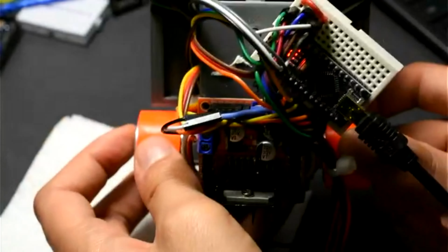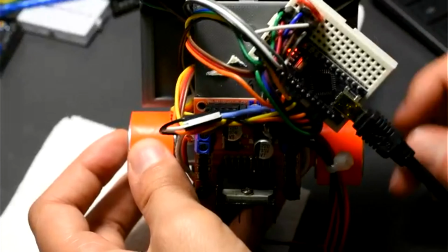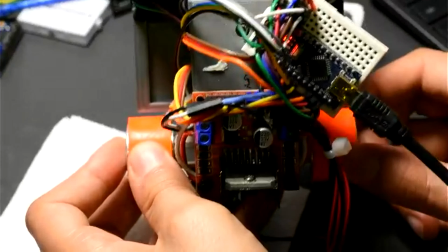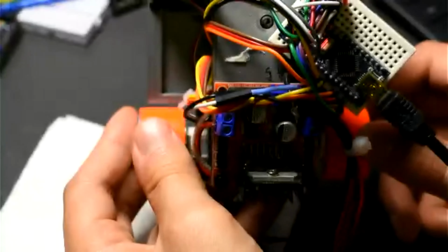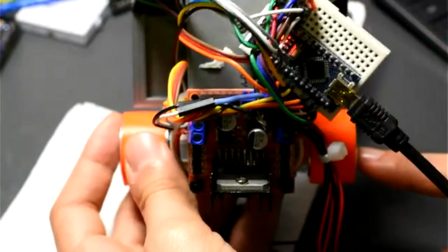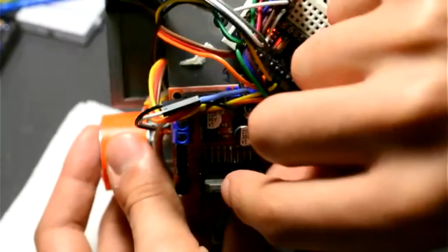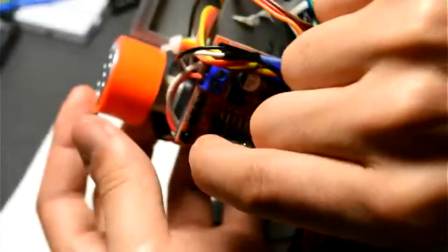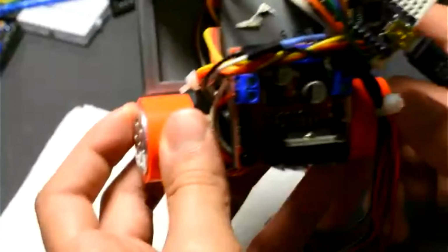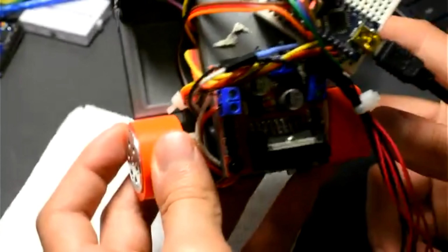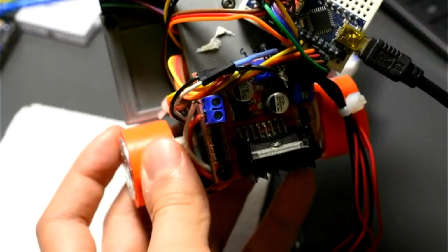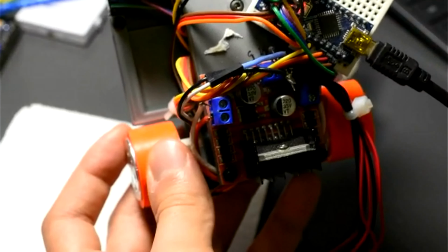And then the third version is to make this wheel go in reverse and this wheel go forward, and it will turn like such. And the turning radius spot will be right in the center of the bot. So this is your tightest turn. It'll do something like this. So I'm going to do something like that for the turnaround method because I need that tight radius.